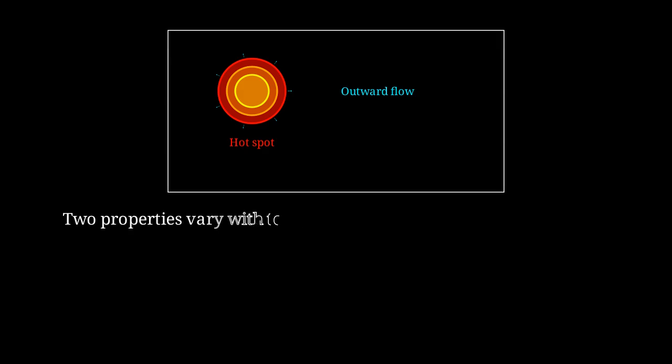Two fluid properties vary strongly with temperature. First, the electrical conductivity increases with temperature. Second, the permittivity decreases with temperature. These competing effects create complex force distributions. The electrothermal force is proportional to the gradient of conductivity times the electric field.